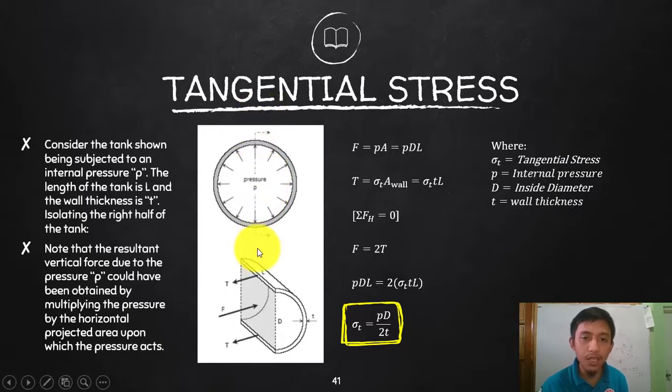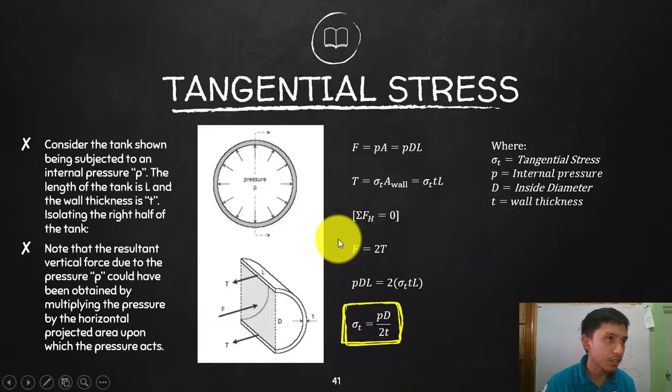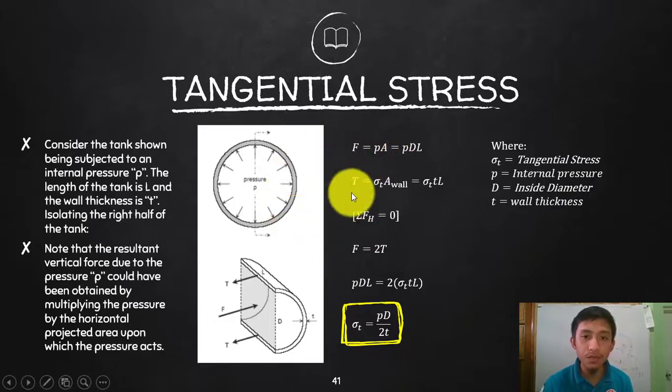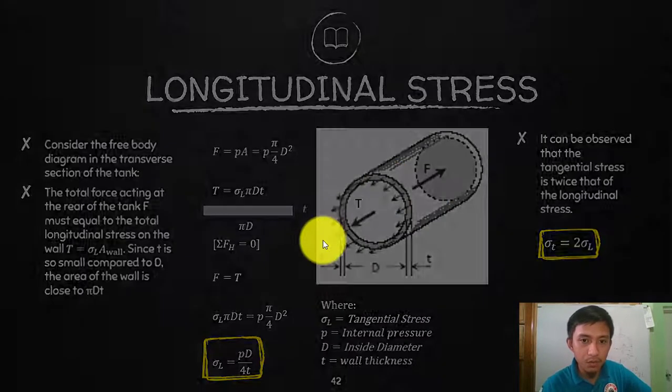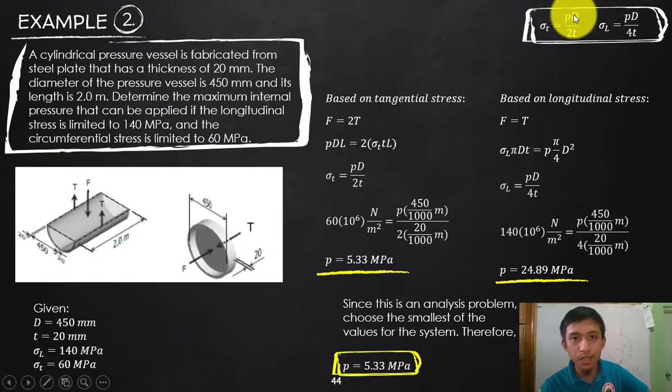Cut at the middle where you will find the maximum pressure, and then get the equivalent force, and then divide that by the area resisting. So the same concept. That is for you to figure out also: apply what you learn here on the other shapes of these tanks. In our case we focused on cylindrical because that is what we derived. But in case your cross section is different, then this is not applicable, because in the first place, if that is rectangle, there is no diameter for a rectangle.